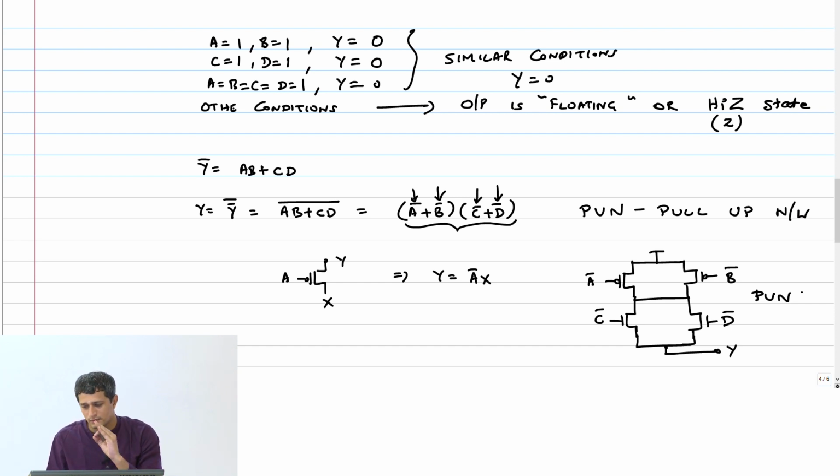So the first useful lesson here is when two outputs are floating in a complementary manner, right? When the output is 0 in the pull down network, it goes to 0, otherwise it floats. In exactly those conditions, the pull up network is going to pull it up to VDD. So therefore, I can tie these two outputs, do a wired OR connection on these two things and get a proper output, right? So to implement this function, Y equal to AB plus CD whole bar.